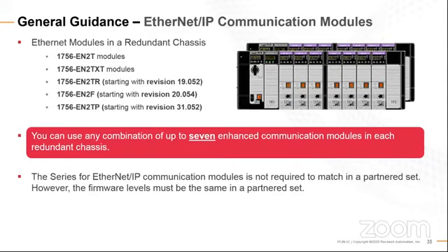Roadmap for the embedded port for redundancy on an L8. It is on the roadmap. I don't have a specific date on when we'll see that, but that one is a future, as I mentioned on the slide. PLC-5 SLC mapping, as I mentioned: we can still do producer consumer messaging. We just, in an L8 ControlLogix design, will not be able to put that as directly into the IO. So we would still have to have that IO mapping at another controller level and then do communication from that.